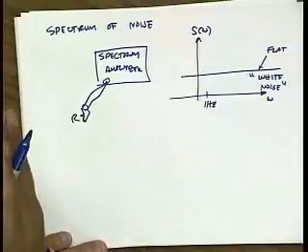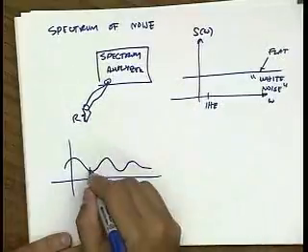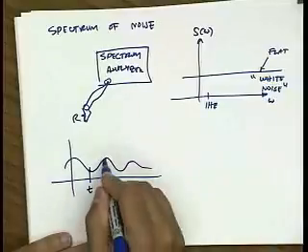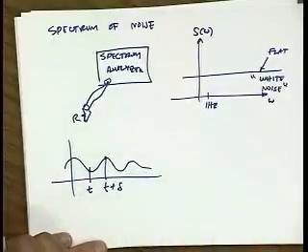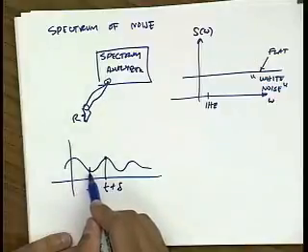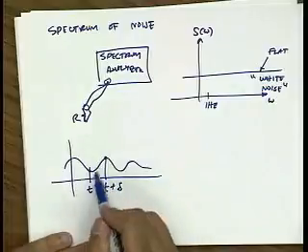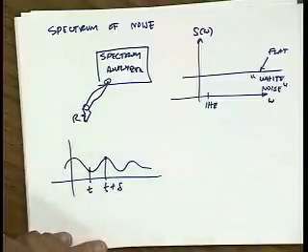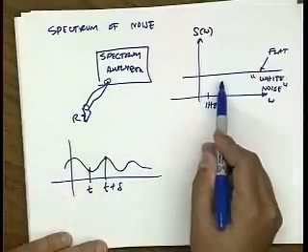If I look at the correlation, so here's a signal waveform, right? And if I examine the value at t and t plus delta, and then I take the correlation between these two signals, because they're close together, you might say maybe they're correlated, right? If this one's, let's say, 1 nanovolt and this one's just a little bit away, maybe it's actually going to be correlated to 1 nanovolt. But you find they're totally uncorrelated. So when I take the expected value of the correlation, I get basically no correlation, that these signals are completely uncorrelated. And that's why, if the autocorrelation function is a delta function, I get a flat spectrum.